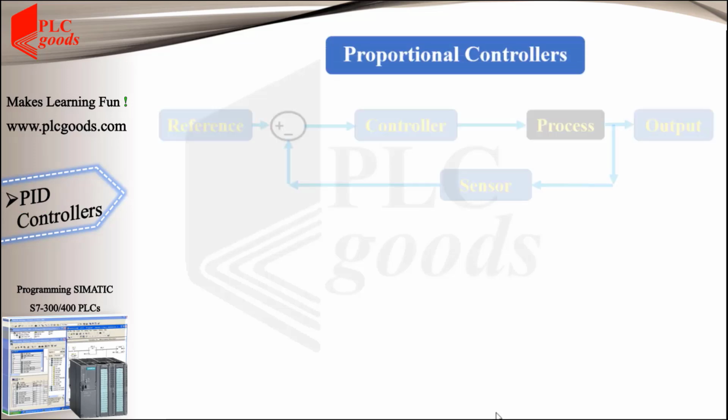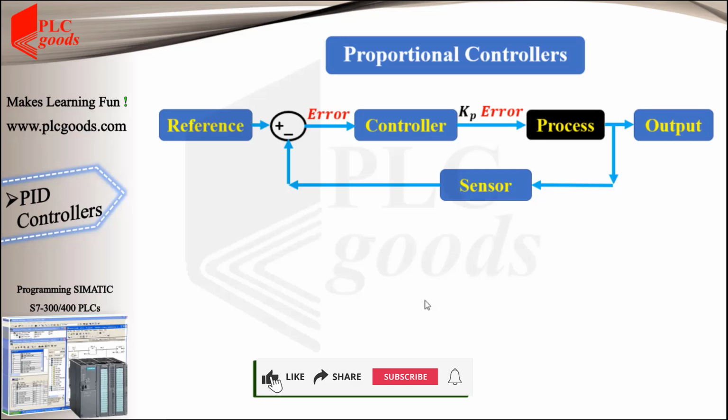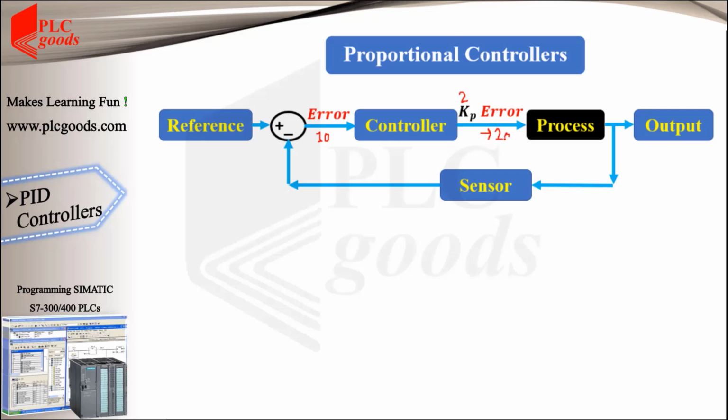First, for the sake of simplicity, let's learn how a proportional controller functions. According to the diagram, a proportional controller multiplies the error value by a coefficient number and applies it to the inlet valve. As an example, if the error value is equal to 10 units and the Kp is equal to 2, then the output of the proportional controller will be 20. For the water tank system, we can assume it is a voltage which should be applied to